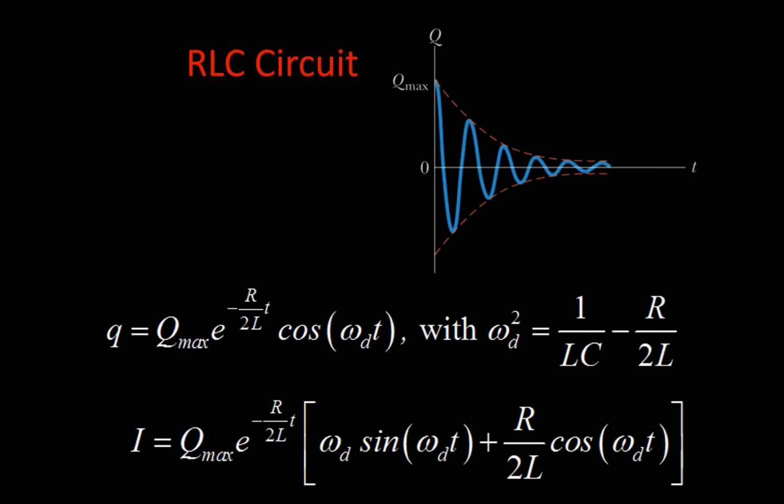So as the capacitor discharges, we've said it discharges over an exponential curve. So here's our Q starting off high and then moving down to low with time. That means we'll start to get some induction, we'll start to get some current back from our inductor, and then as charge diminishes, our inductor slowly reduces in its energy output.